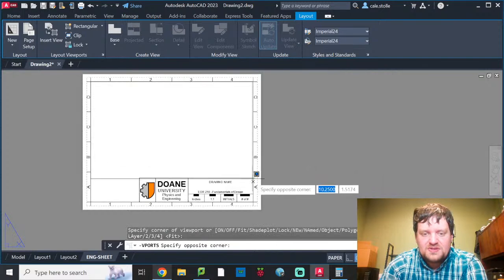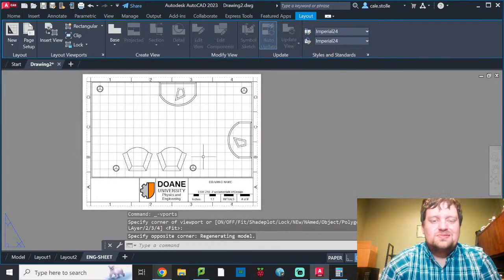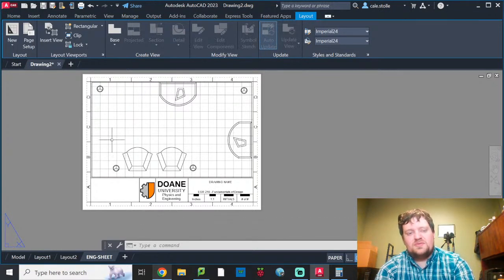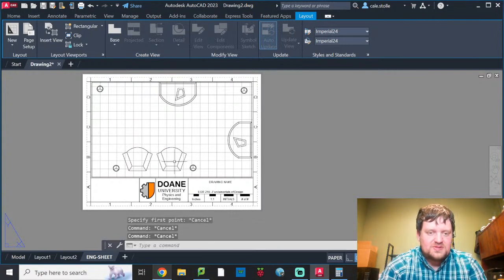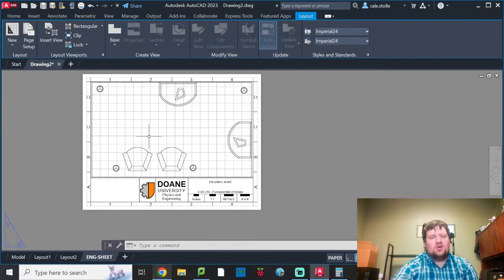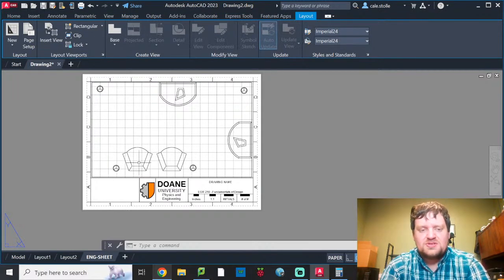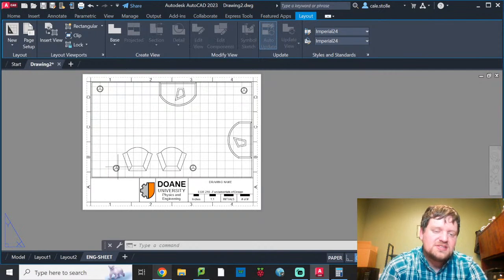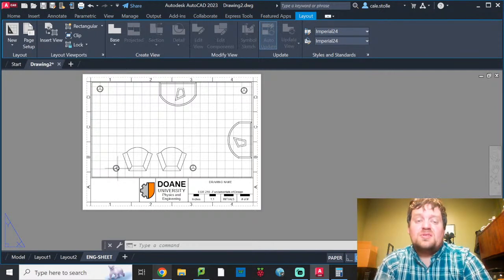Now, as we put this in, we're going to be drawing this to scale. So as it is right now, when you draw this on your page, if I were to try to figure out what scale this is, historically what's had to have been done is you try to dimension as much as you can. Because the more dimensions you have, the easier it is for things to be read. So I would dimension what is the size of this recliner, what is the width, what are each of these component sizes, how deep is it, how long is it, what position is it in the room, what orientation is it in the room. You have to dimension every single one of those aspects.